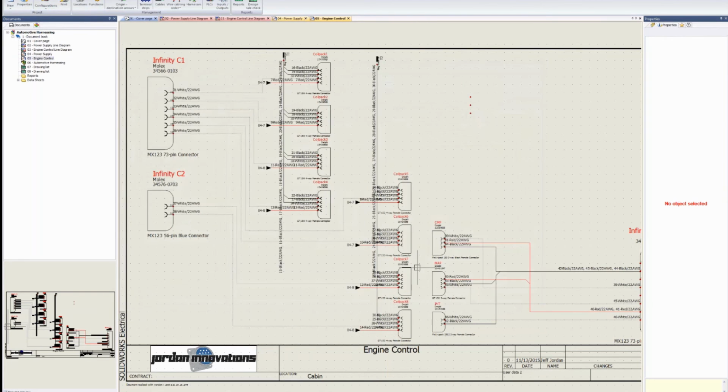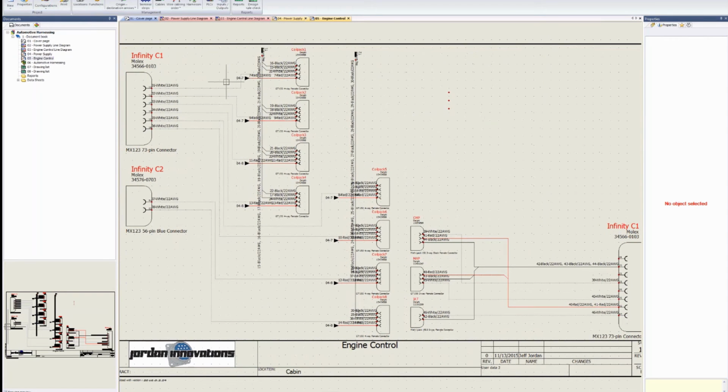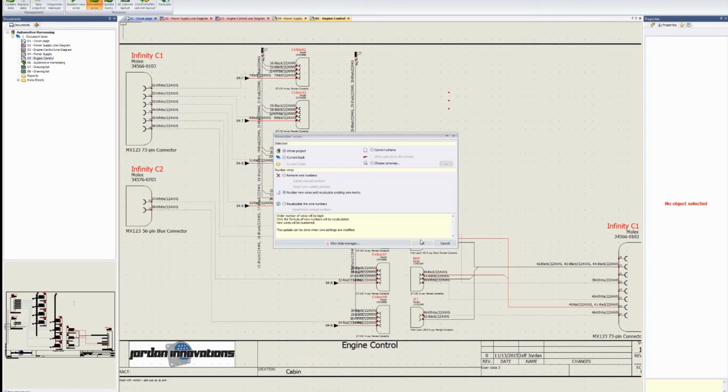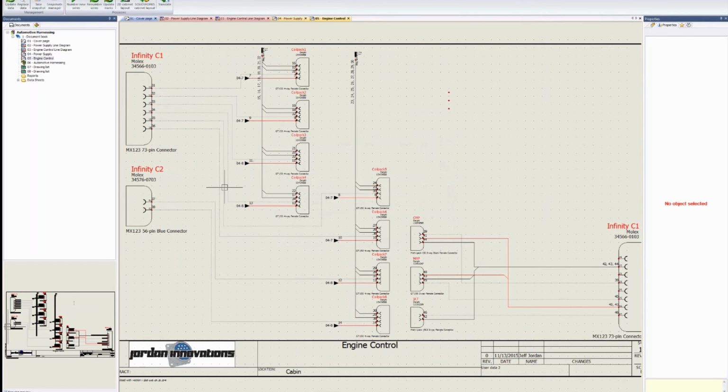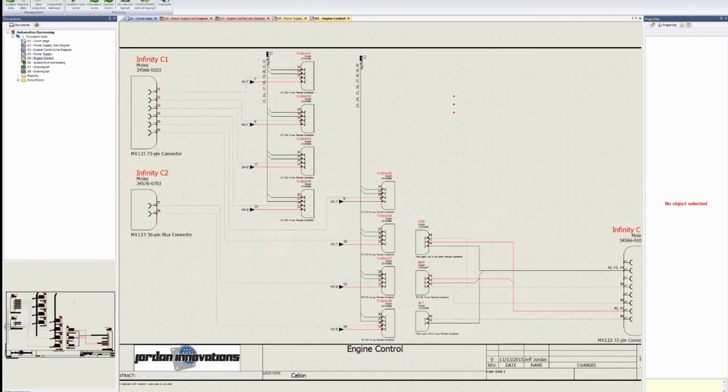And then, can you imagine cleaning this document up if this was in AutoCAD? I'd have to click every single one of these. Not into that. I'm going to say, hey, renumber based on the new formula, and 2 seconds later, we're back. So I've just got individual wire numbers. They're still unique, but this is going to track all the way through my project. All of my single line stuff gets updated, all of my multi-line stuff gets updated, and all of my 3D stuff gets updated when we go to 3D.